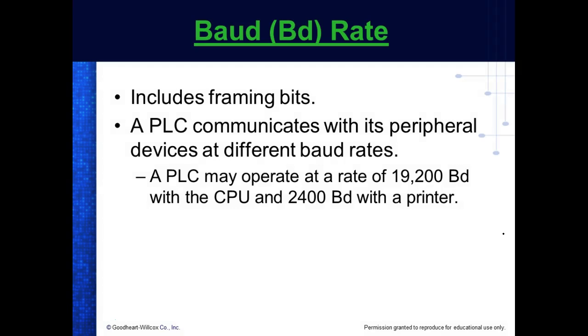Baud rate, basically, is the speed of the serial, and it's usually labeled in kilobits per second. It gets a lot faster, but you need to look at the interface to see what it is. This is the problem we have with using this one: the fastest it supports is 9,600 bits per second.